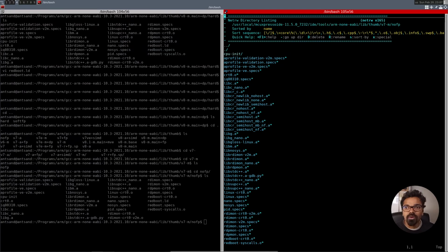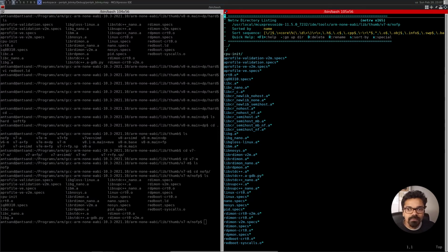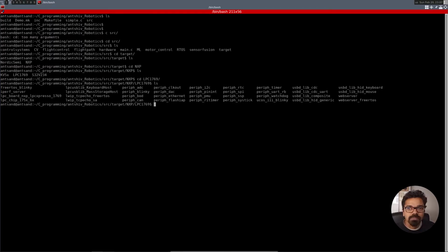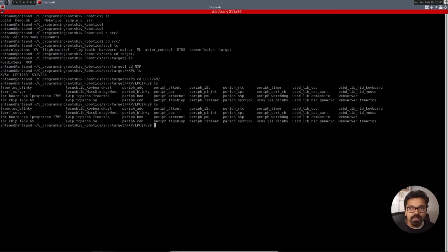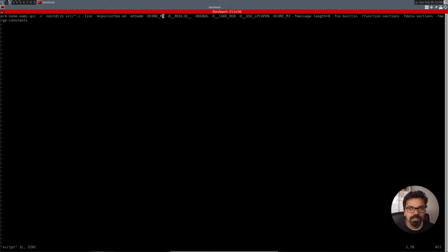So I basically copied all the libraries that are very specific, that this manufacturer expects me to link to for this particular target. I take those and I link them with my custom directory. So now when I go to my custom directory over here, I have my file. In my previous video, I went over here and created a small script. I'm not using make for right now. I created a small little script that runs GCC and creates all the preprocessing directives that it needs to be compiled for.